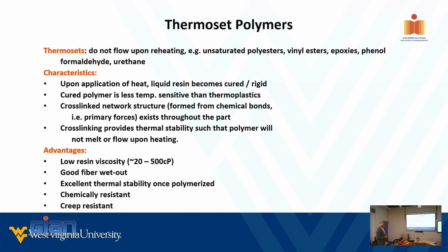So I talked about this in a way. In the olden days, when I started this business of composites, we had a heck of a time getting low viscosity resins. We were primarily dealing with fairly high viscosity resin, that is 2500 to 3000 centipoise.